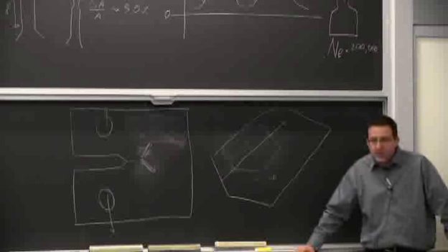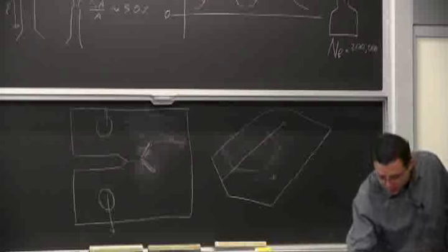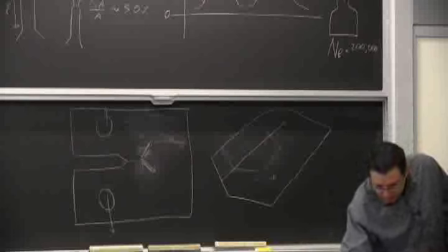The grains, the crystals, sometimes the precipitates may trigger turns in the fracture path. That's an example. So you see it's really going at 90 degrees for this specific crystal, because that's where the shear can actually take place. Shear can't go straight through, so it has to go up and down at plus or minus 45 degrees.